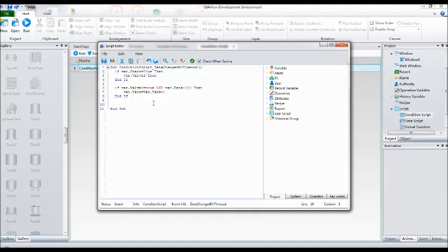So next, what is our requirement? We want to have automatic filling and draining. So if variable tank is equal to 100, filling should stop. If the tank is completely filled, then val1 should be off, that is false.